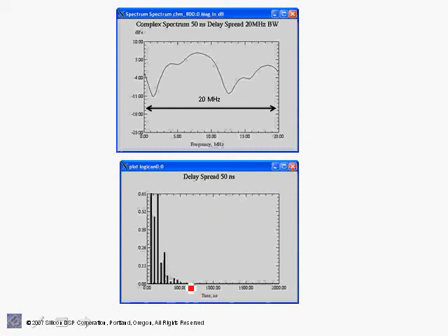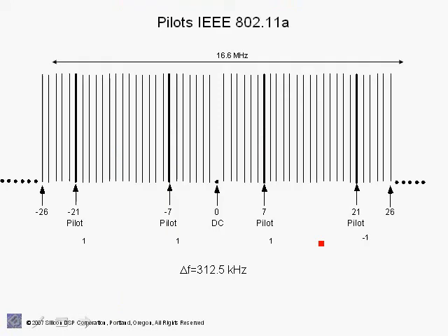We see the exponential decay, and you can see that the impulse response dies out after a certain number of samples, and this is the number that you associate with L. So for example, in this case, if we use 1, 2, 3, 4, 5, 6, 7, 8, 9, or 10 pilots, then we can estimate the channel perfectly with 10 pilots. That's what the lemma in the previous slide showed.